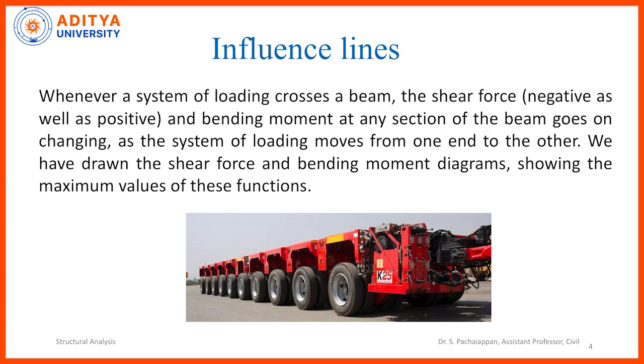So far, we have computed the shear force and bending moment values, and sometimes the deflection values, in a cantilever beam. All these values are fixed quantities, because in a building the dead load is not going to vary. Even though the live load varies, when we design the structure we design it for the maximum load. So we do not consider the live loads in the building as actually moving.